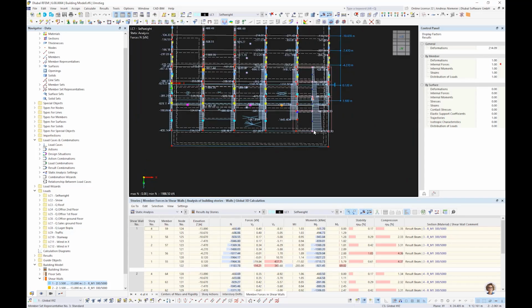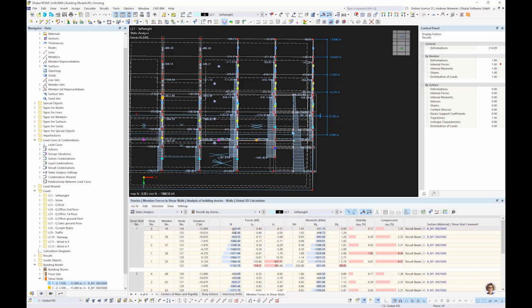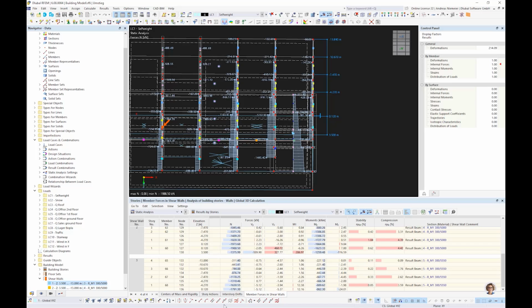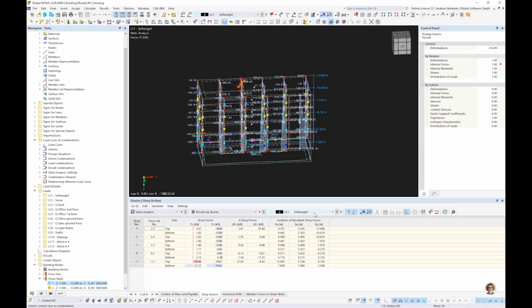And if I define it as wall, the program interprets it like a beam. Yeah, and all these forces you get locked down here in this table for every load case. You see the increasing normal force in load case self weight for wall 1, wall 2, wall 3, you get, let's say, story actions. These story actions are interesting if you take a look, for example, on wind.